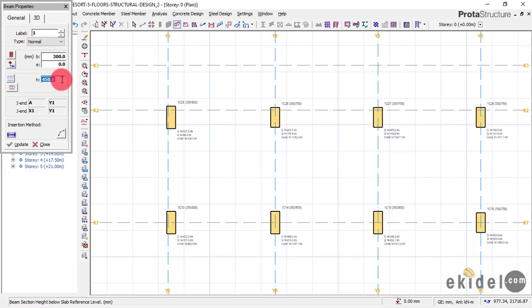And then for the depth now, the depth basically starts from 1 meter. So whenever you are designing for a Raft foundation, the first thing you have to consider for the depth is to start from 1 meter. If it is below 1 meter, that means you are going into a wide strip foundation. But from 1 meter, that's why we start our depth of beam for Raft foundations. Okay, so right now, since this is a 5-story building, I will not consider using a 1 meter depth of beam.